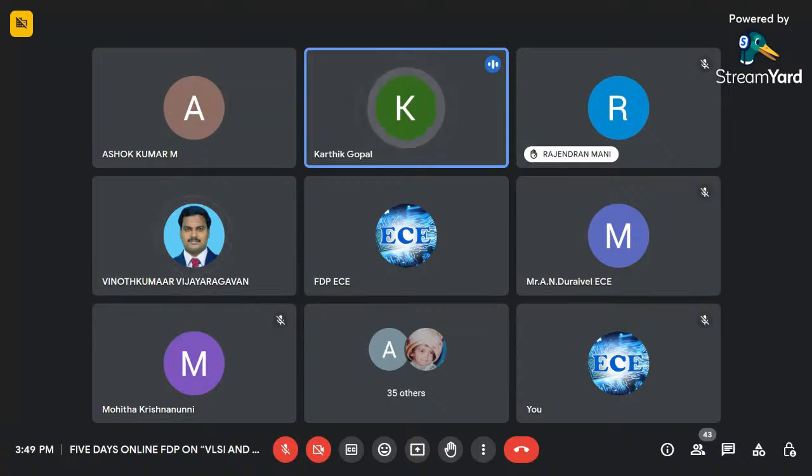So I have given 1 kilo ohms, because if we give certain values, it will settle at that value. Earlier, if you see, my output DC was close to 1.7 volts. We should be able to know where we need to reduce that voltage to make the op amp work. That is why I increased the resistor to bring it down. So these are all intuitive methods we need to implement in circuit design.